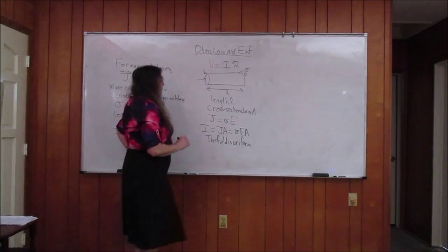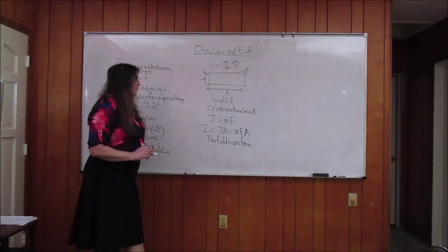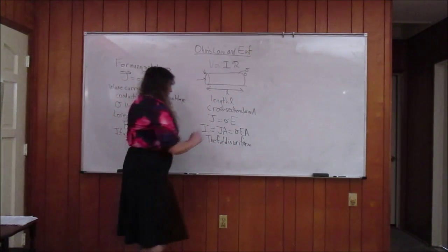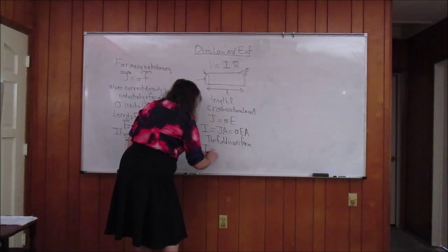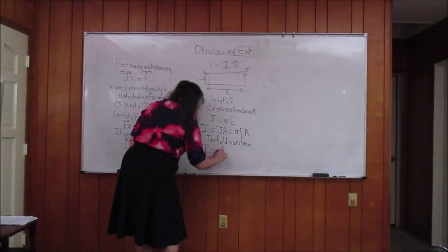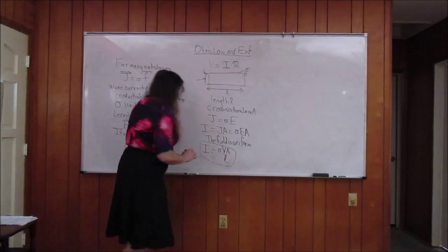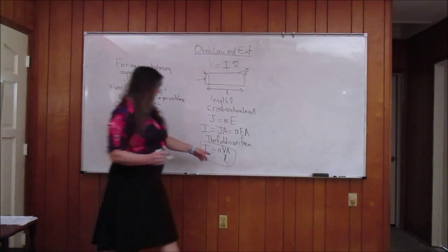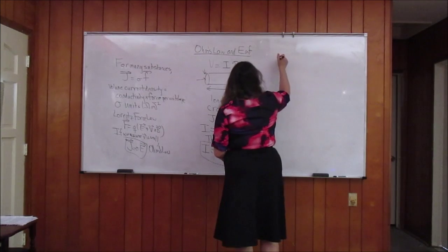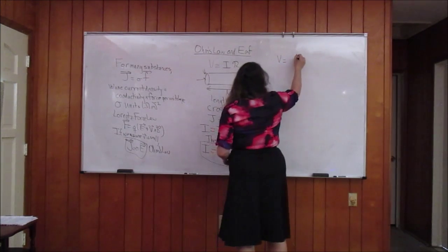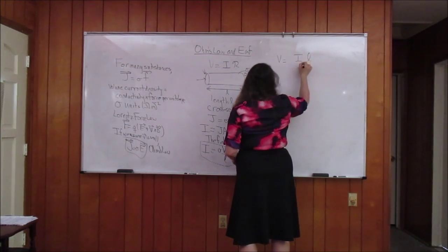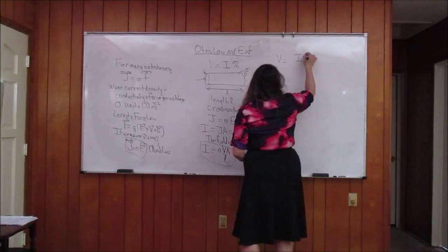So if the field's uniform, that means I can immediately write down the electric field in terms of this potential difference in length. Therefore, current is equal to sigma times potential over length times area. Now if I compare this expression with Ohm's law, maybe write it a little bit differently: V is equal to I times L over sigma A.